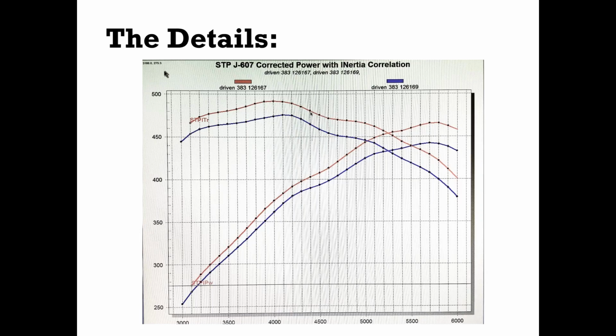And we probably all have the same experience. You can pour the oil up to a certain point on the dipstick, walk away for 10 minutes and come back, and then check the dipstick again. It's going to be even higher because it takes time for the oil to make its way from the valve cover down to the valley, down to the oil pan. And the heavier the oil that you use, the colder the environment is, the longer it's going to take. So you have to be very precise in the amount of oil in the engine.